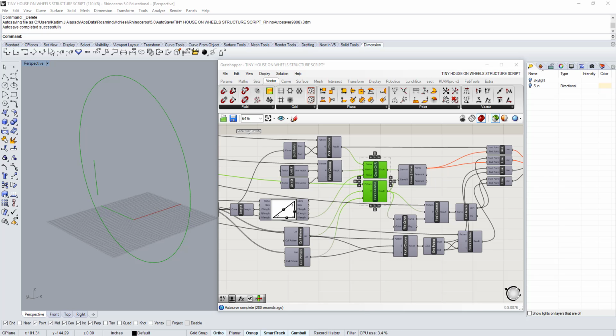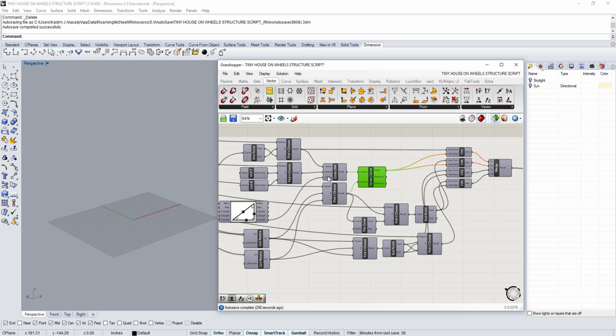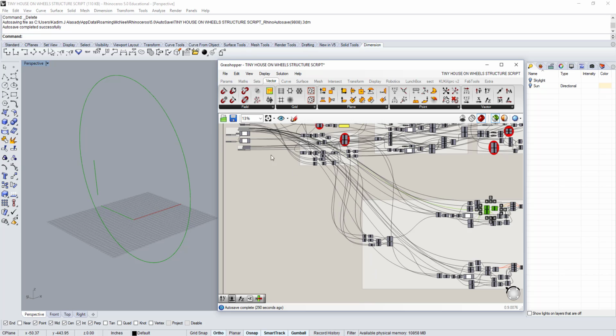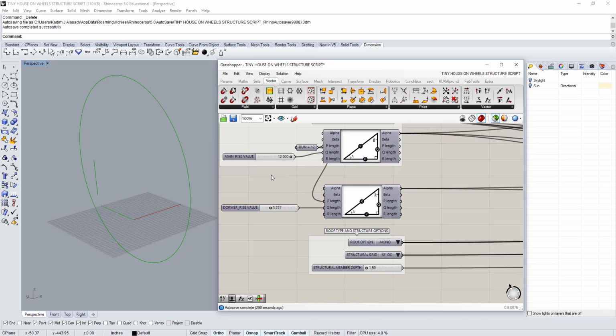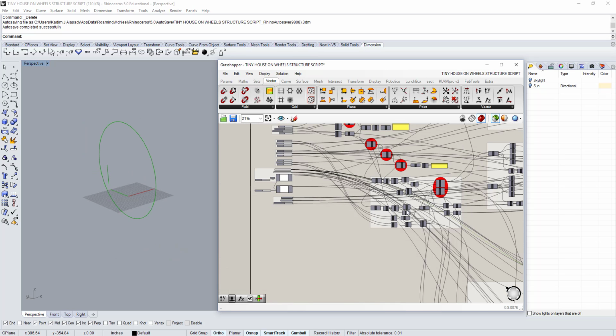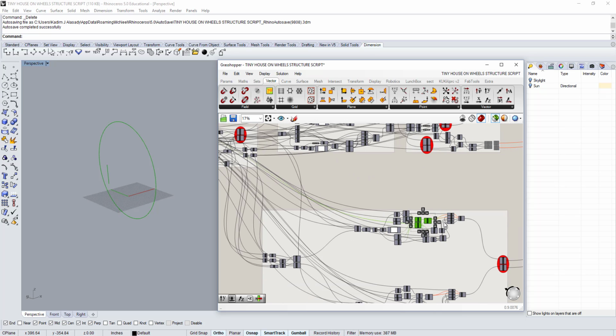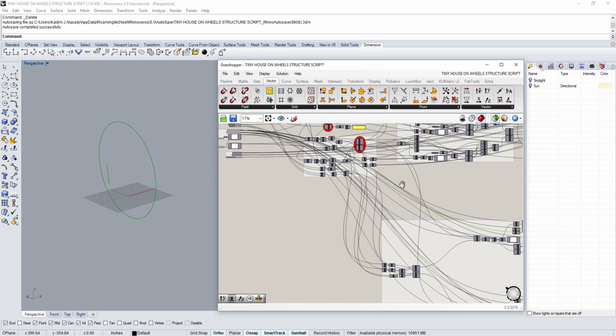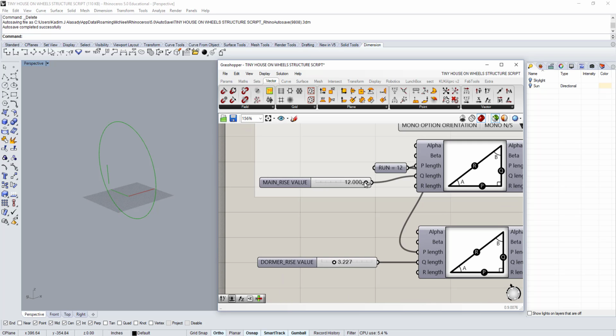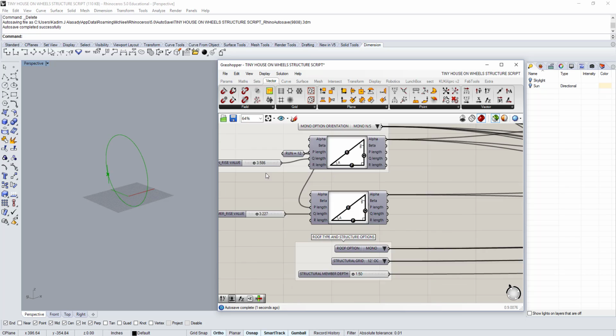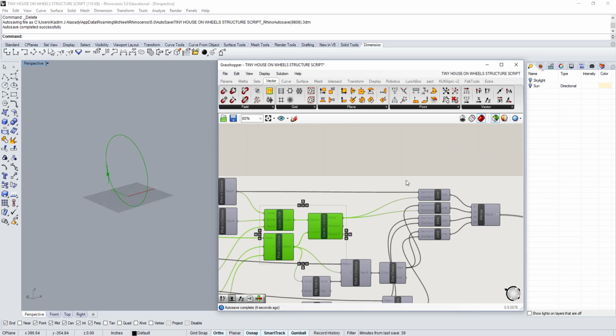That error there is from the fact that this slope is so large that when the roof is oriented north-south, it simply misses that long edge. So I think that error there is actually accurate. When you get that error, that means you set the roof slope to be too large for this structure. So we're going to actually change that for demonstration purposes. There we go. So now that error shouldn't be there.